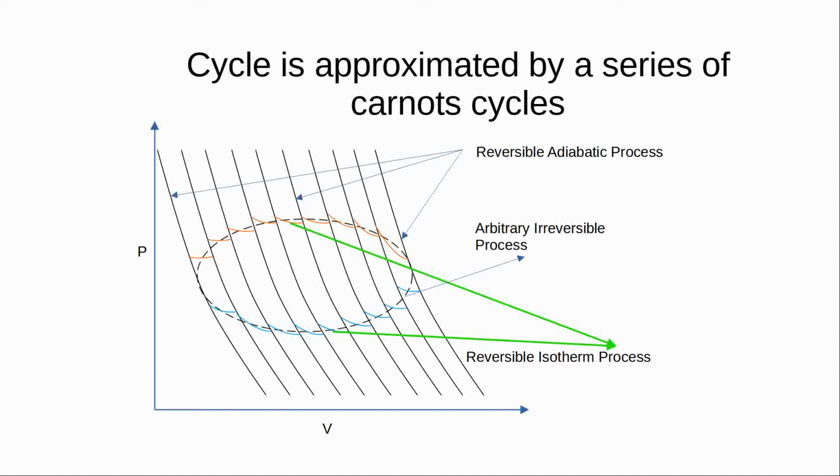reversible Carnot cycles. Now each of these reversible Carnot cycles does work adiabatically but reversibly and takes heat isothermally reversibly and rejects heat also isothermally and reversibly. Now these are the reversible adiabatics for each of the processes. So each Carnot cycle is within these two reversible adiabatics. The heat is received with this isothermal reversible process and the heat is rejected by this isothermal reversible process.